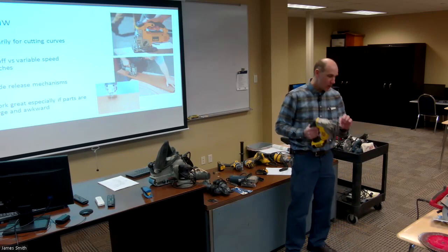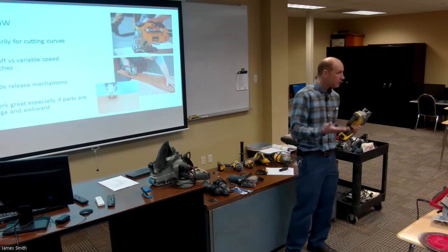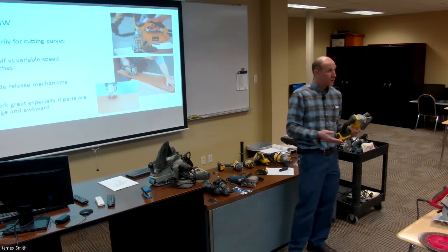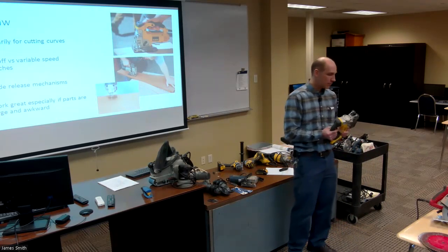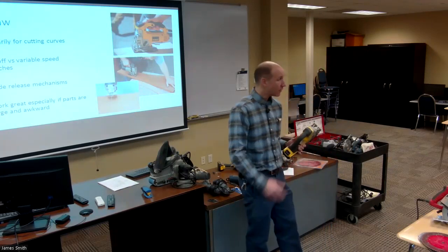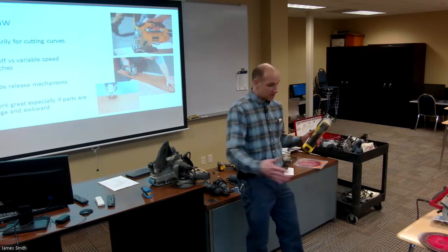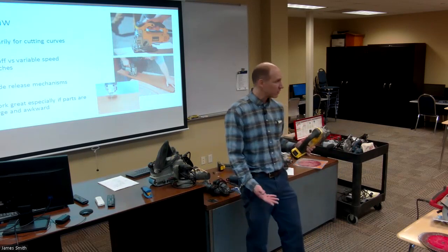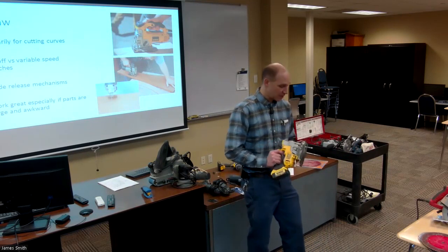Okay, but notice the blade width. All right, what's the purpose of this saw? For cutting curves. Okay, so is it the best saw to cut curves with? No, not necessarily. I mean, best, that's kind of a relative term, right? It really is determined by personal preference. I know for me, I would rather use a bandsaw, but I may not have that. Or maybe the circle is so big that the bandsaw doesn't give me the clearance to do it, or it's really awkward to try and turn on a bandsaw table. And so in that case, this would be the best saw to use for that.